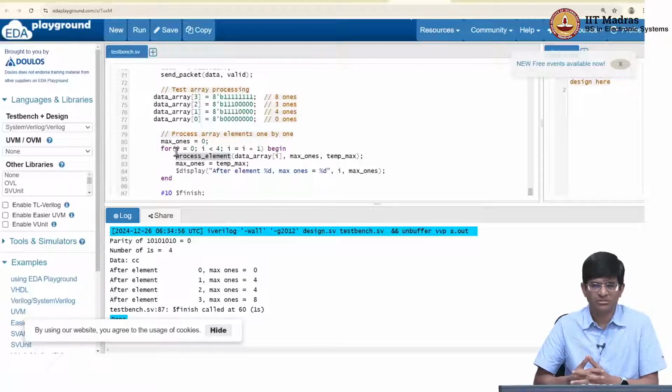Okay, so the reason for using tasks or functions, a very important thing to keep in mind, they make sense mostly only in the test benches, right? But they can be very powerful to increase the value of the test bench in the sense that they make it easier to use and easier to extend in various ways, right? So judicious use of these kinds of things can make your test benches much clearer to understand and also easier to reuse and more modular.